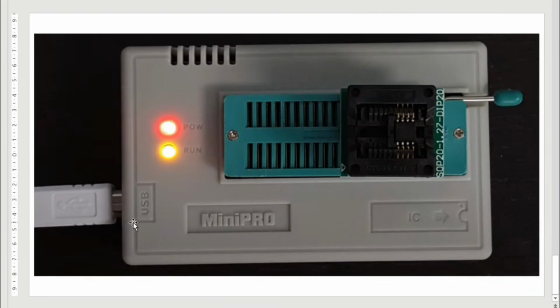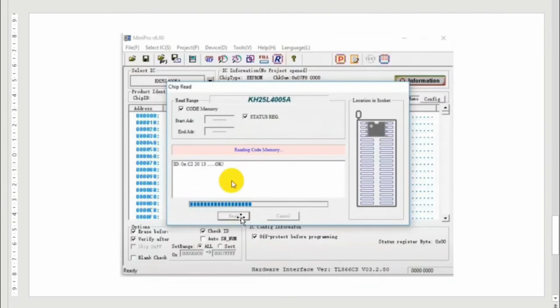When you program the BIOS, as you can see here, in the EEPROM there are 2 LEDs. This LED is for the power, and the second LED is for run. Once you launch the program process, the run LED will be lit until you get here finish, or the BIOS programmed successfully. Okay, so now I will go right now and explain to you the software interface.